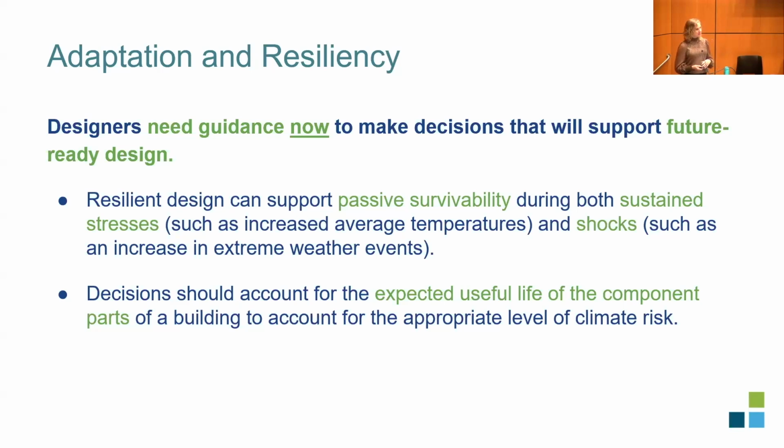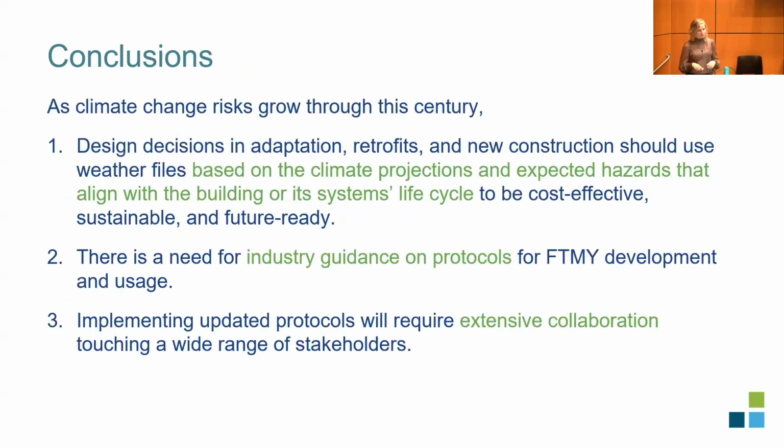When you're making these decisions, I think it's really important that you consider the expected useful life of the component parts of the building. The weather file that you're using for your HVAC system that lasts 15, 20 years is probably different than the weather file that you're thinking about for your foundation and your envelope design, which is going to last many decades into the future. So think about how long that component is lasting and then pick something that has an appropriate level of risk.